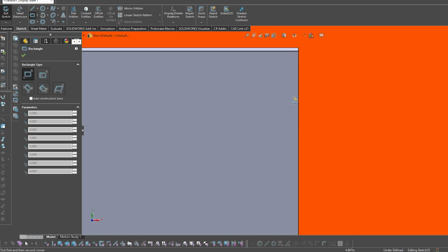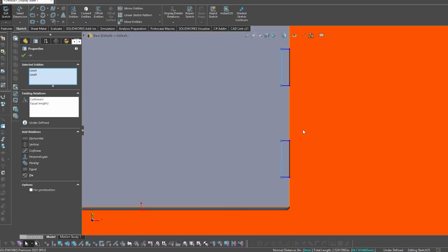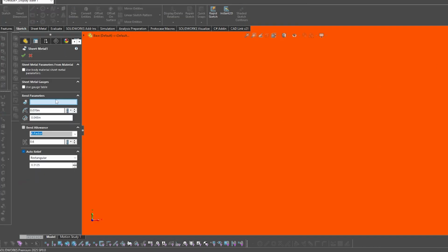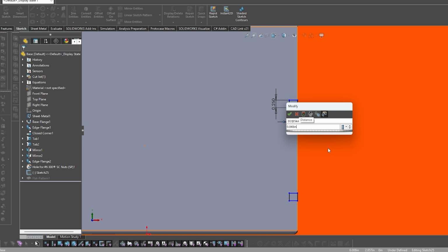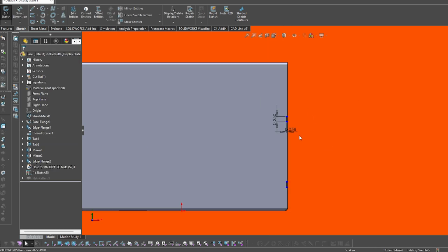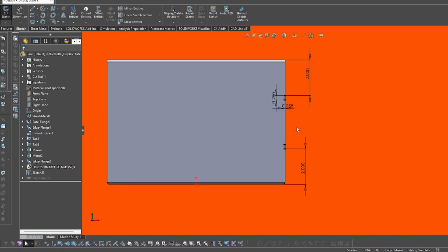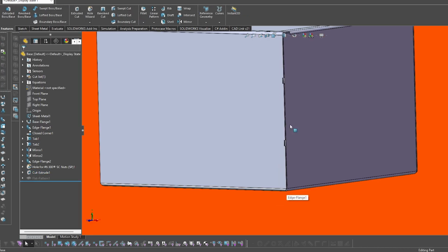Start by evaluating your design and pinpointing which corners will benefit most from tabs and slots. These are often high-stress areas or places where alignment is critical. Design where the tabs and slots should be for maximum structural support. Ideally, the tabs should be placed along one side of the corner piece with corresponding slots on the mating part. Ensure that your tabs and slots allow a snug fit without excessive tightness.